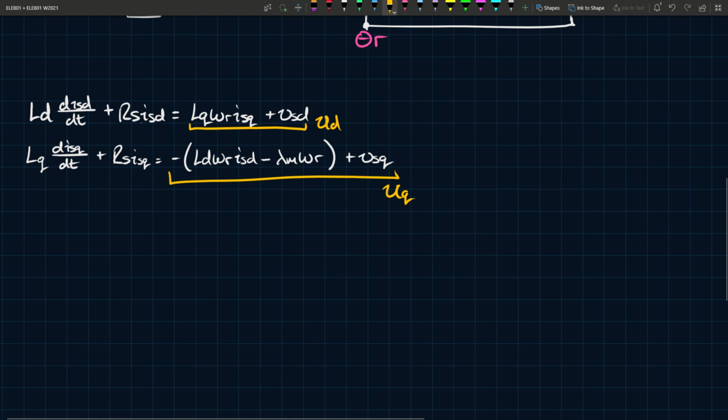So remember, the left side of the equation is the plant, which is the 1 over s plus whatever it is. Well, in the general case, it's 1 over tau s plus 1. And you can have specific cases where it's equal to a bunch of different things. So why don't we first take equation 1 and turn that into a control loop.